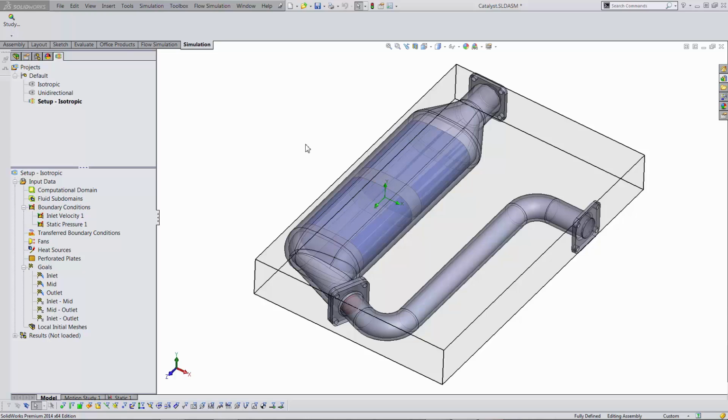And that's why they started using this porous media instead. What porous media does is use a pressure drop versus a flow rate that we tell the software. So we tell it what we expect the pressure drop to be, and it just pulls that data from a chart. So that's how it's able to simplify that.